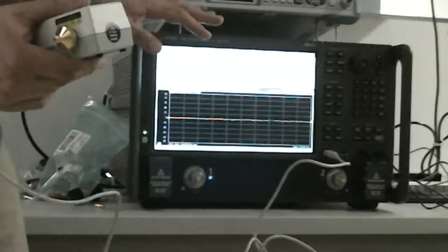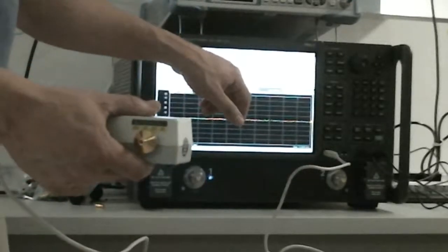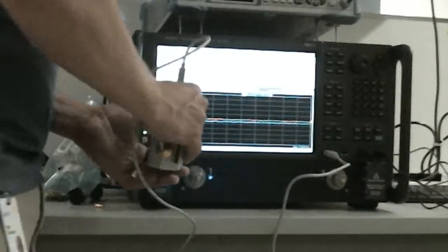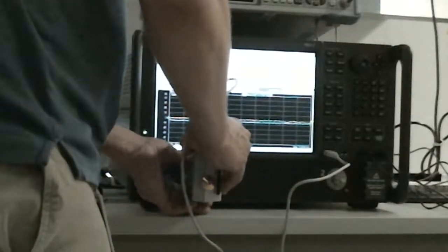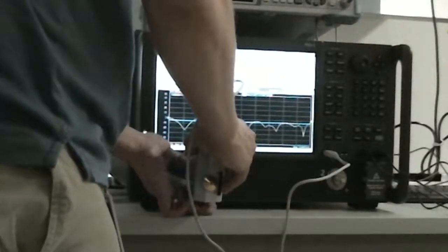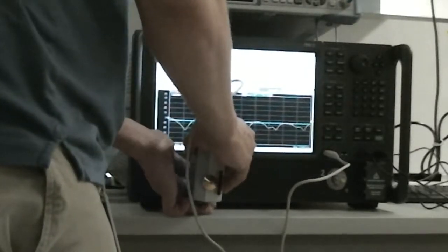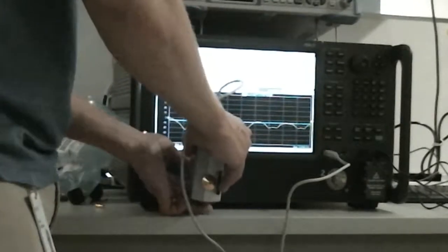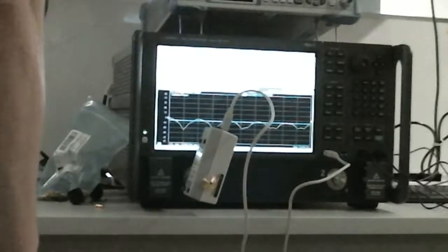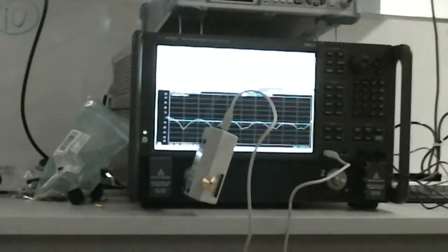It automatically detects the eCal and says that's the one you want to use, and now it's going to ask me to do some measurements. The really nice thing about a male-female eCal is it gives you full flexibility in terms of what kind of devices you want to measure. So if your device is insertable, meaning it has one male port and one female port, you can easily calibrate that.